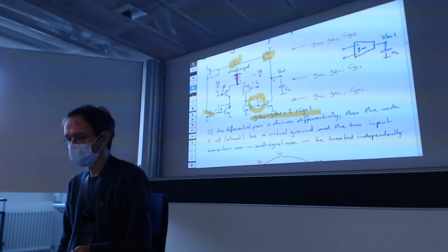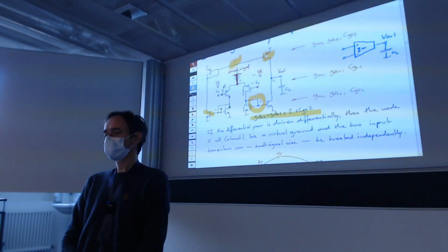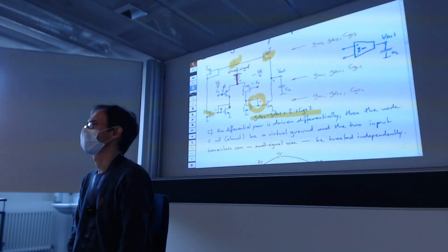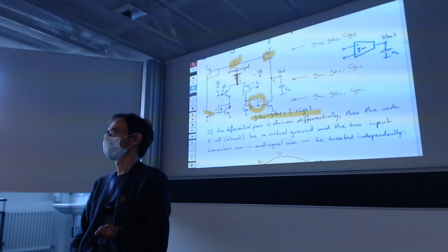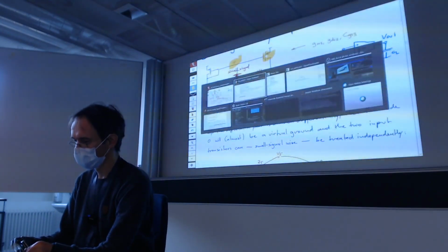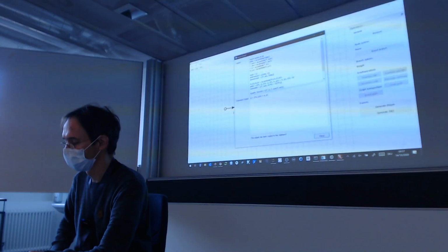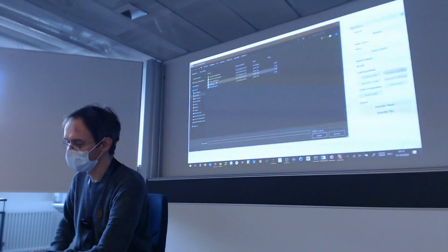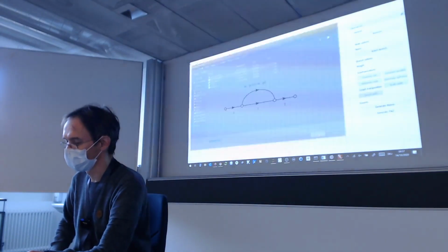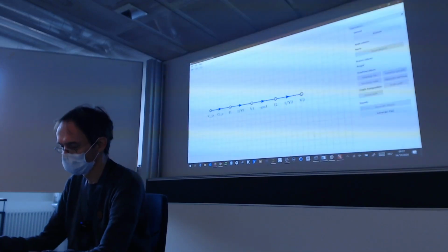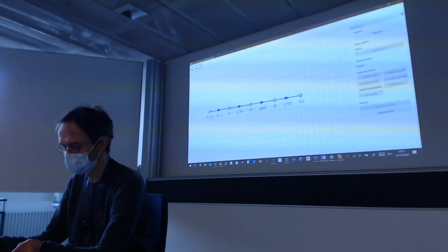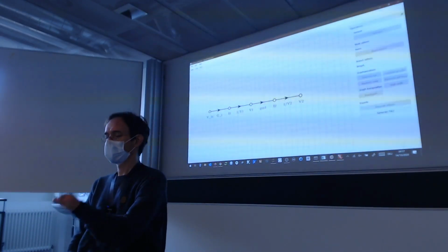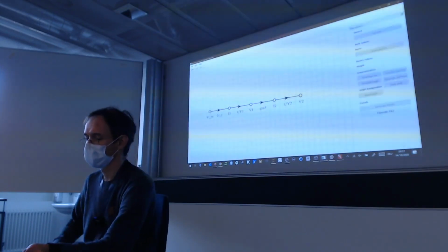You have to be careful, of course, when you do these short circuits, because these short circuits do not take into account that you may have some feedback around everything. And so this ad hoc method is okay, but not always. For example, we saw one counterexample here when we just looked at the common source amplifier. This gives me the chance to put it back on the grid. When we looked at the common source amplifier, we just got the signal flow graph like this, which was straight, and the poles were where they belonged.